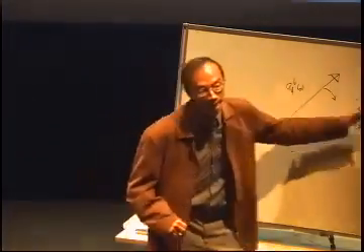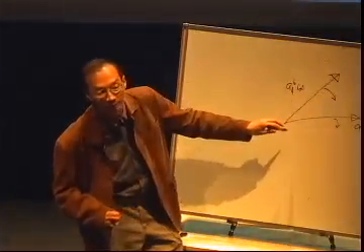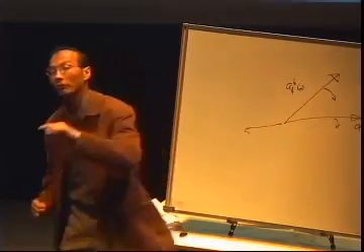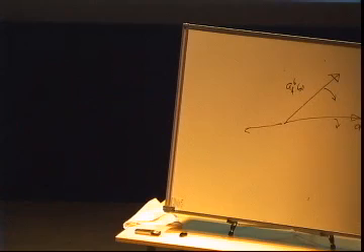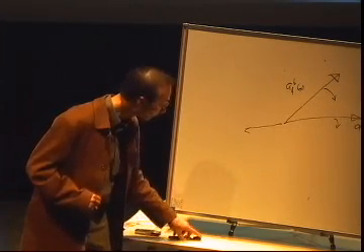We have a peak. When this guy becomes 180 degrees off from this guy, there'll be cancellation, channel becomes weak. So as you move around, the channel will become strong and weak, depending on whether you have constructive, destructive interference. And so you have variation.